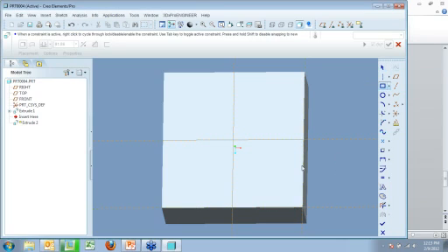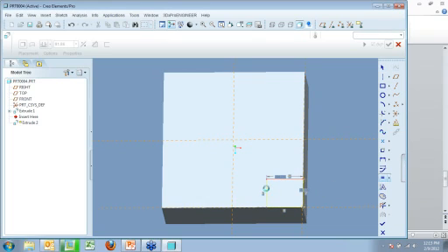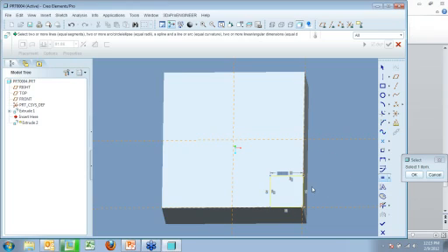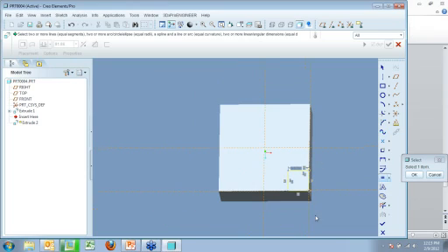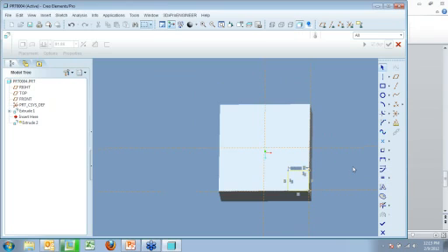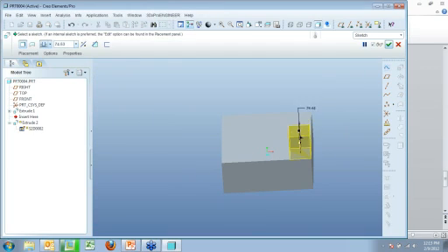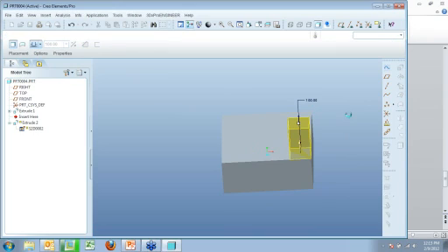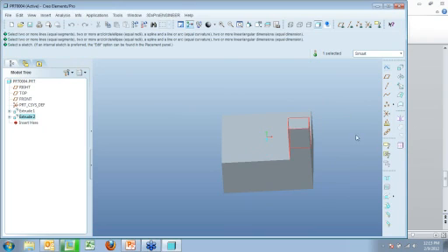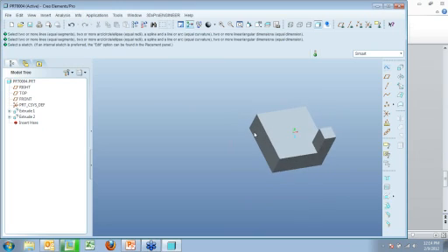So now I'm going to go in. I'm going to create a square that snaps to these 2 points. I'm going to go in and make it equal again, which I could have done without, could have dragged from that corner up and done some on-the-fly constraints there, and that would have worked just as well. Now, again, have to come down here and click this check mark, go in and drag it to where I want it, or we'll make this one 100 tall as well. Excuse me. So there's the part I'm going to make.